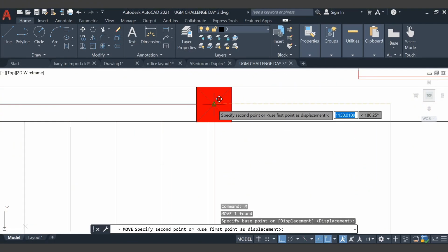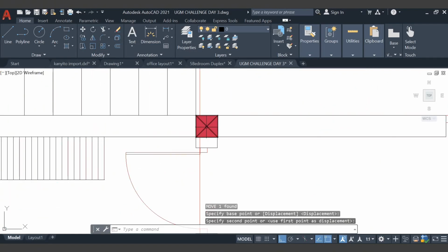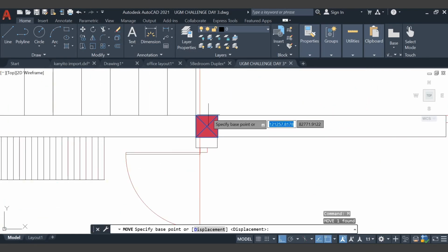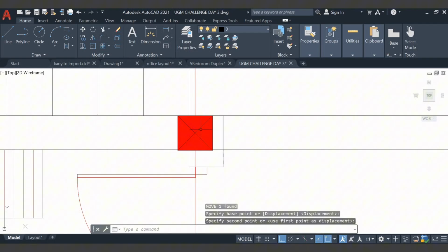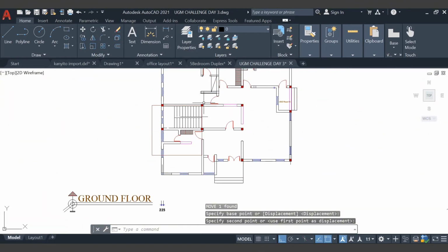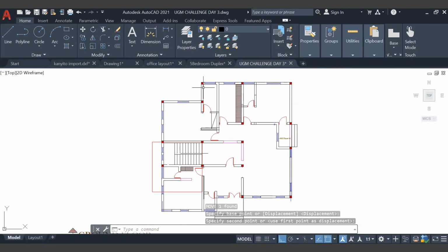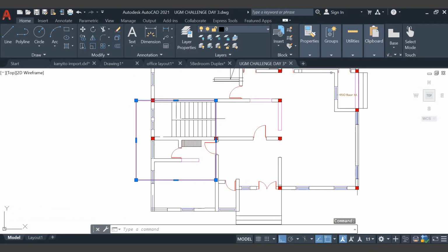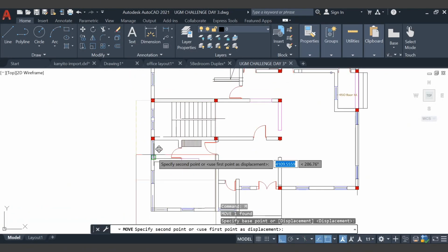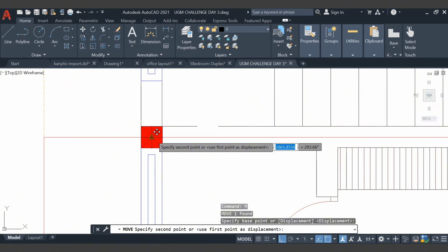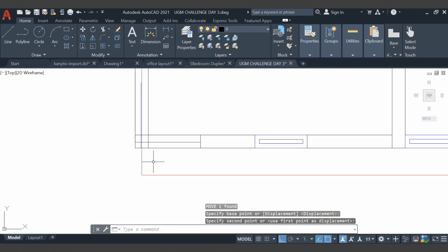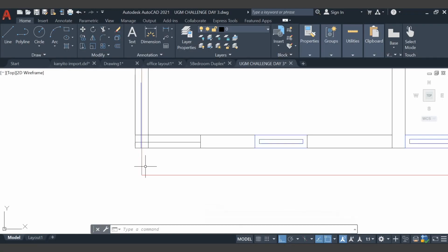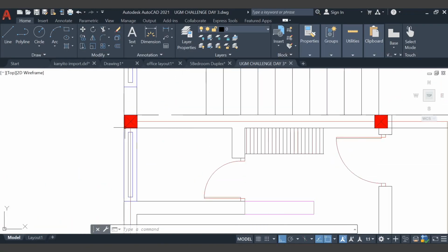so you have a very good structural grid running on that side. So now you've put them in line, and they're also in line with this other two. So you move the panel guide, place it over here. You can see that you can place a column here, but it's already outside of the perimeter of the building, so you just go ahead and place it right at the edge.